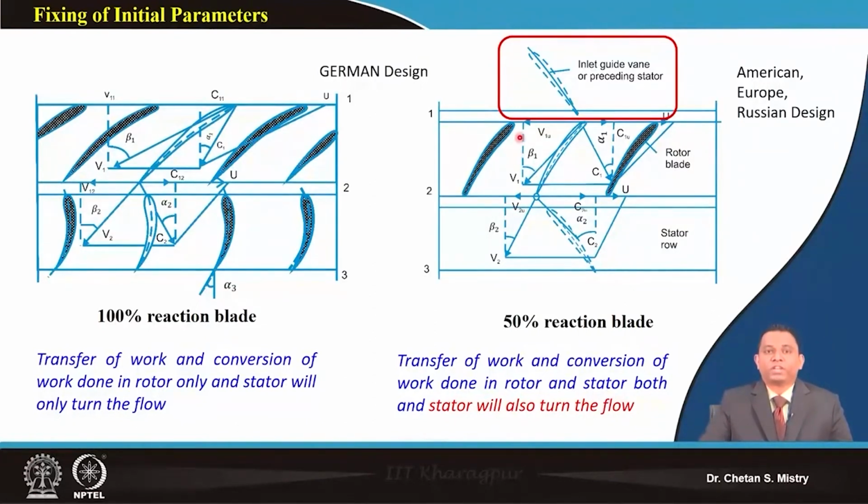So this is giving some guidance: when you are doing design for a particular kind of stage, be careful. In later stages, maybe the third or fourth stage, we can move with a 50% reaction design configuration, which will avoid needing the inlet guide vane. So in initial stages you will not go with 50% reaction, and in later stages you will go with a 50% reaction design. This is a design philosophy, and when you are doing your design you will learn all these aspects.